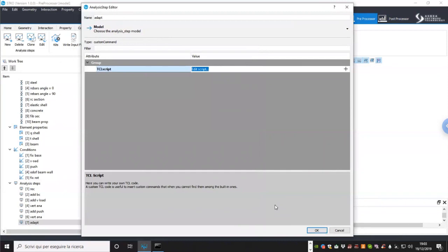Next question from Professor Filippo. Yeah, the fiber discretization in the cross section now. Yes, they use Delaunay triangles. Now you cannot specify a quad discretization because we are adding it right now with basically a quadtree mesh. So basically, we will use just quad meshes that will refine where the cross section has smaller features. So it's going to be implemented soon.